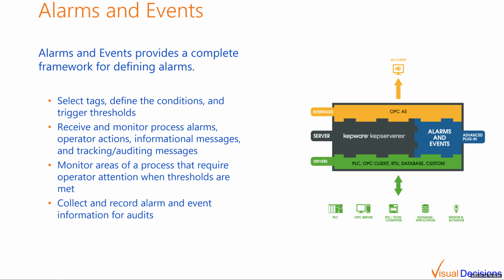And those alarms can be handled and translated into text messages or emails, etc., and get sent out to anybody that needs to pay attention to that particular alarm. So by putting this right next to the device itself, as you're collecting that data into Kepware, you have the ability to have those alarms happen very quickly and to take action based upon that.